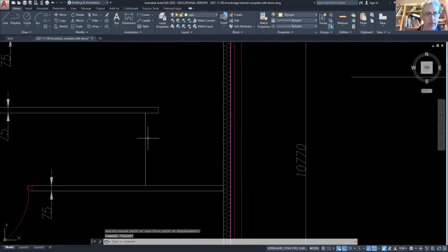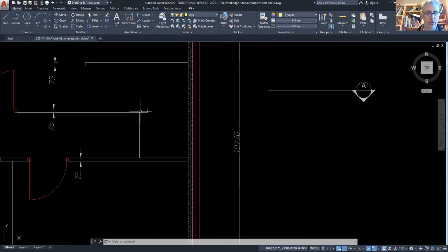But getting back to this particular stair that we've got now, we're going to offset that by 225. Okay, 225 is something that's going to be fairly good to get the stair pitch that we're looking for. And you'll have done some calculations with Chris Wood's class about how to set up a stair pitch. So go to offset and then type in a value of 225 and then enter.